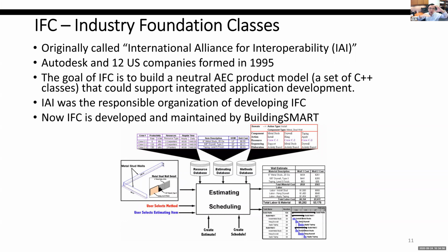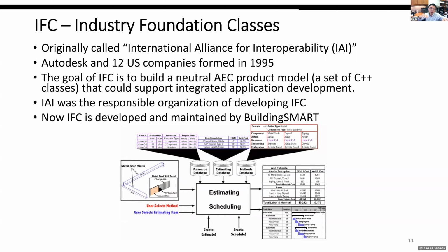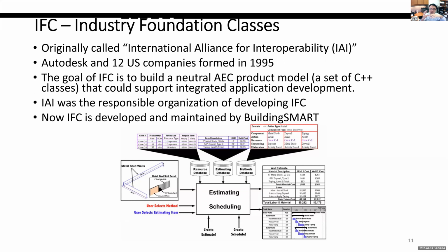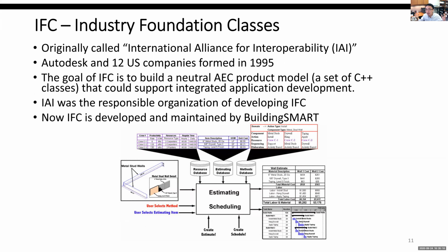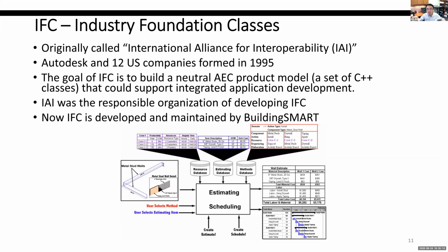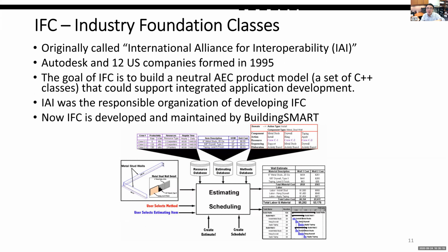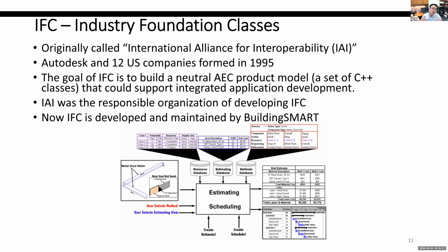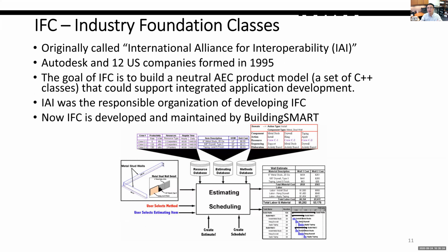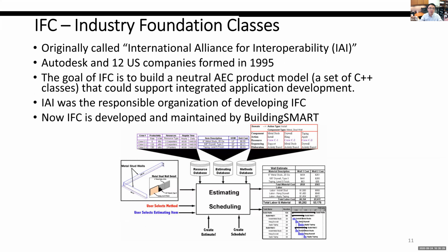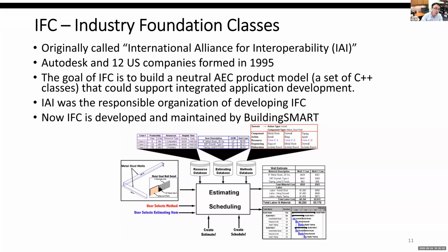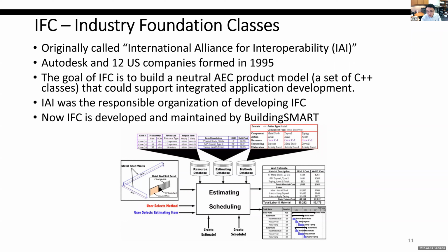So if I have a floor, or a ground, a concrete pad, and I try to attach a light fixture to that, you would receive a warning inside the program. So the computer can become smarter and knows that relationship. And we don't have anti-gravity. So if I have a table, it must be sitting on the ground. So table on ground. The "on" actually defines the relationship. So Industry Foundation Classes is nothing but a very clear, very strict description of everything and the relationships among them inside the building. That is extremely important for computer programs to understand.